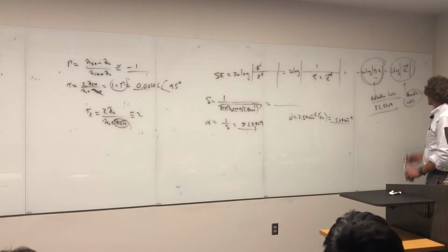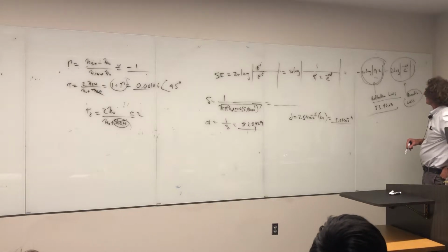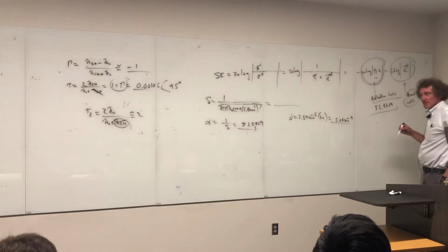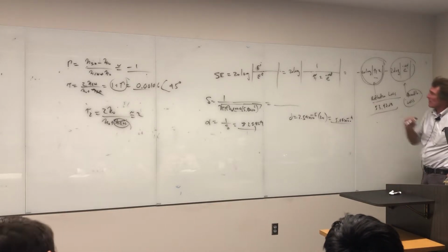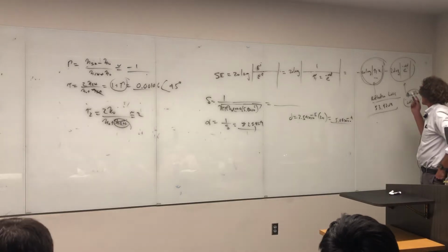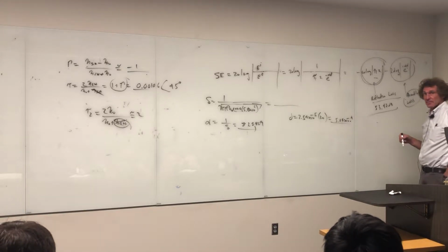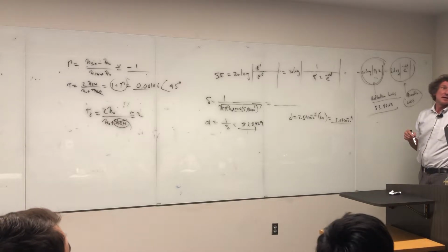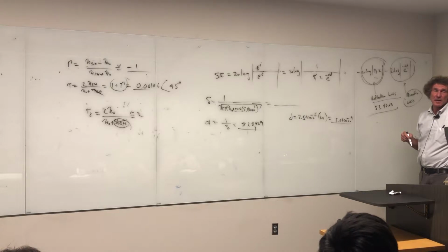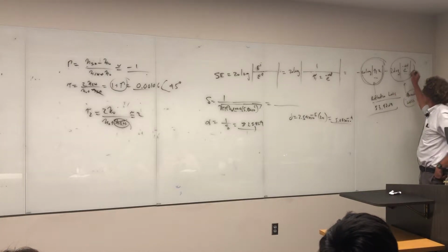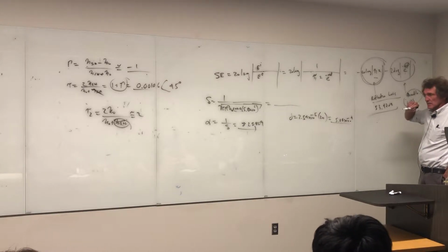So what do you get for this? Just tell me what the absorption losses are. First, get e to the minus alpha d. There's a starting point. So there's d, that's alpha. Multiply them, get a product. Take e to that value, then take the log base 10 of that times 20. Anybody? Positive 3,657. Log of that? That's 20 log. E to the minus that? What is this number? It's a negative 420.